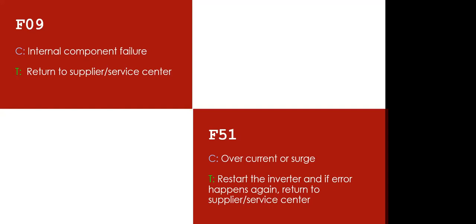Whenever we want to do troubleshooting and restart the inverter, we should know that the battery must not go first. The battery must go last. So you turn off the solar first, the input breaker, which is grid, then the output. Then after that, you turn off the battery breaker. When you want to restart the inverter, you start from the battery. You turn on the battery breaker first.